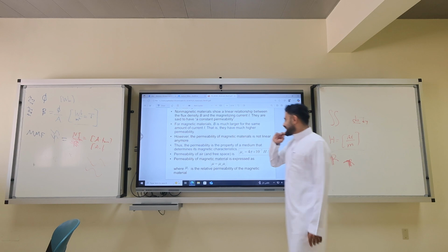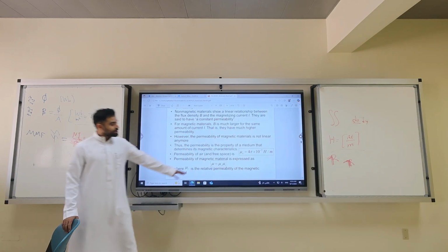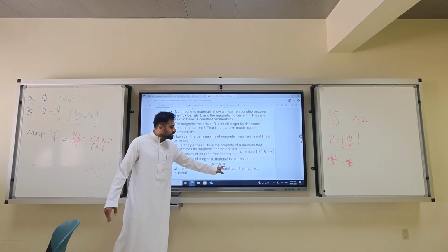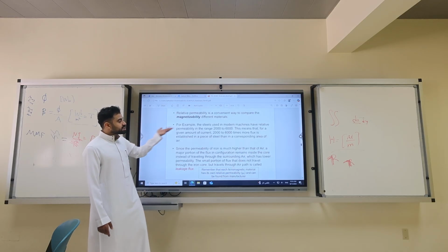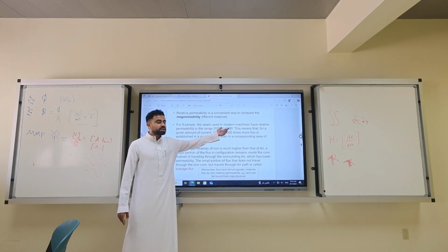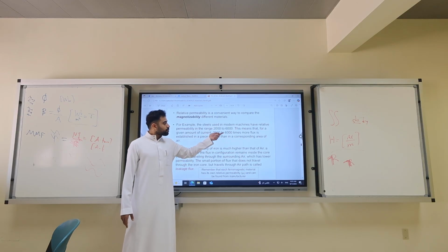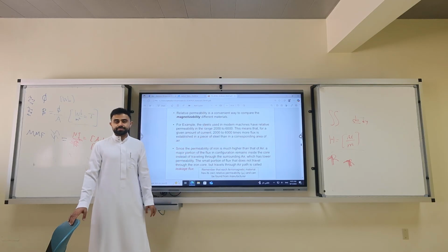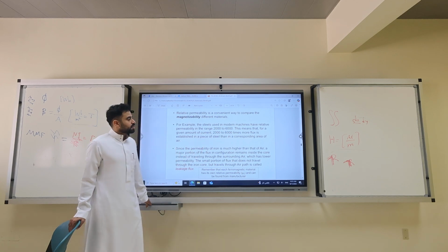Okay. Now, what is mu? Mu is mu naught times mu r. What is mu r? Relative permeability. Mu naught of the air. So you're measuring relatively with the air. There are numbers. For example, the steel has some of the good steel, expensive steel, 6,000. Cheap steel, 2,000. So 2,000, what does it mean? It's 2,000 times better than the air or a vacuum. 6,000 times better than the air.